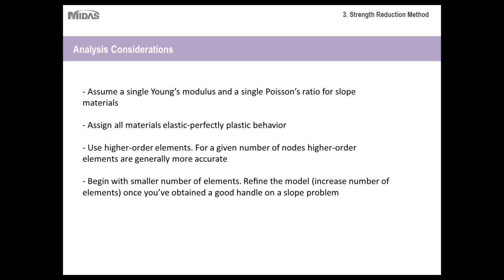This will help you cut down on the analysis time. If you have larger elements, the analysis runs much faster because it is less detailed. But later on, as you're refining your model and getting closer to your submission, and you've accounted for all of your design changes, then at that point you can use smaller elements. That way you can get a more detailed analysis.